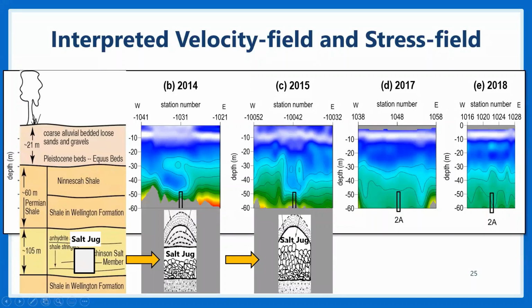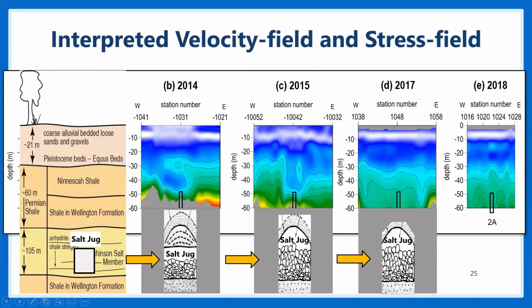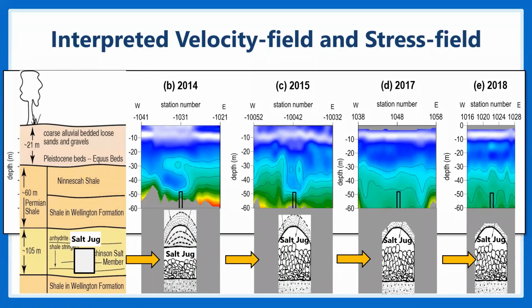Potentially in 15, some of that material may have collapsed, or maybe it's about to collapse. And then in 17, because that collapse has happened, the loading on the void itself is more evenly distributed. So we don't necessarily have this tension dome structure anymore. And so it's now able to exist under its own self-weight, and hopefully not further collapse, because if it did, we would have seen it at the surface. But fortunately, that has not happened for us here at this specific borehole location.